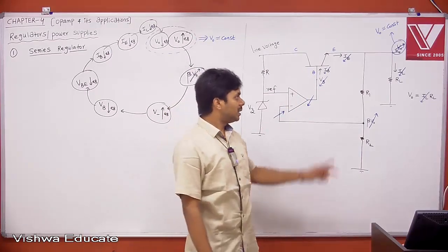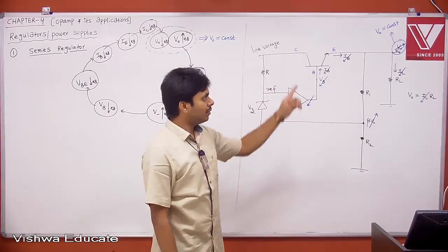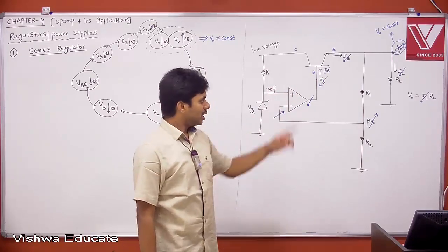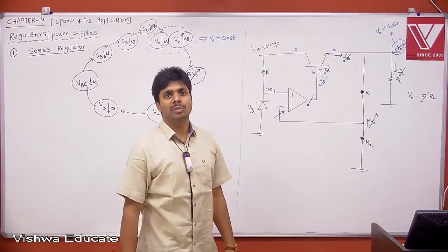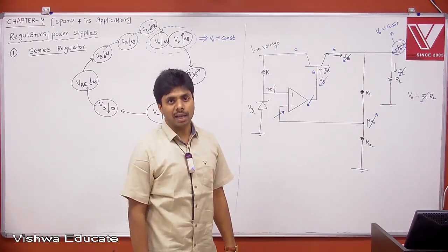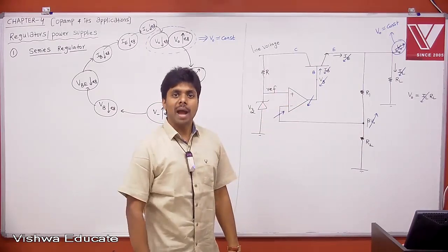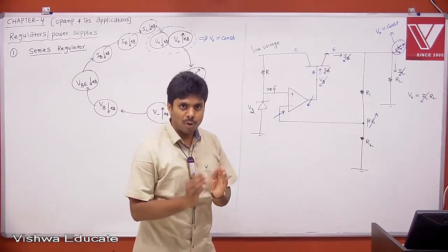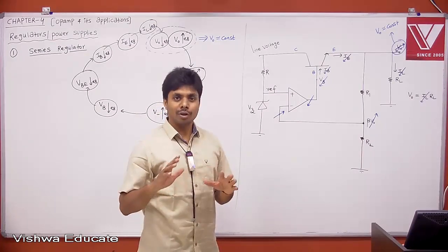Let us say your load is changing suddenly, then definitely V0 changes. Then it will take some time to settle and then it will give you a constant output voltage. This is what people call loop settling time. That is because of the loop bandwidth. The loop bandwidth will be lower to get more phase margin or gain margin. I will not go into those details.